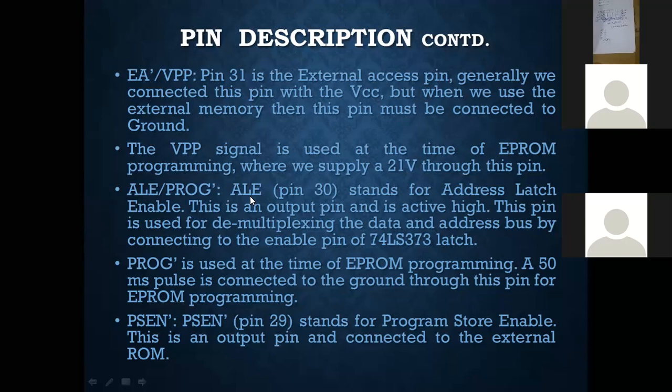Yes, but please remember that at the time of EPROM programming, we need to use some microcontroller program burner. During this program burning operation, a very high pulse is to be given to this pin only, and this pin is designed in such a way that giving a high pulse to it doesn't affect the microcontroller. This is not the operating voltage; it is a voltage that is given only at the time of program burning.